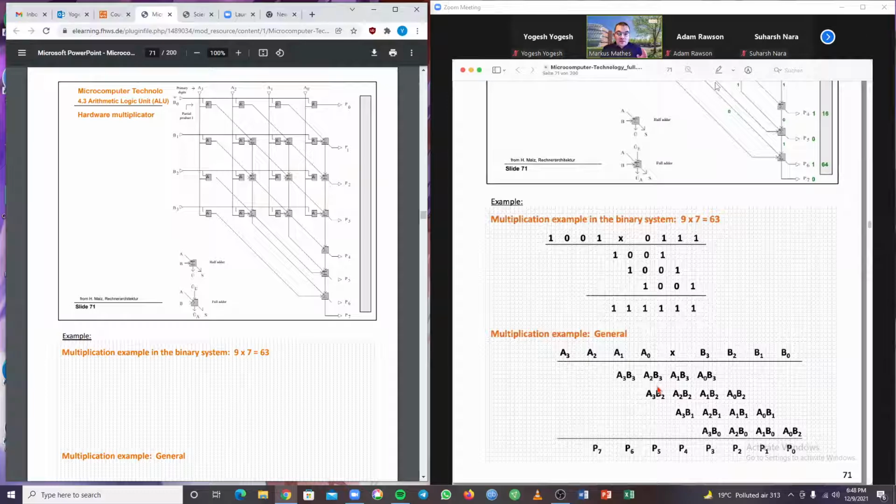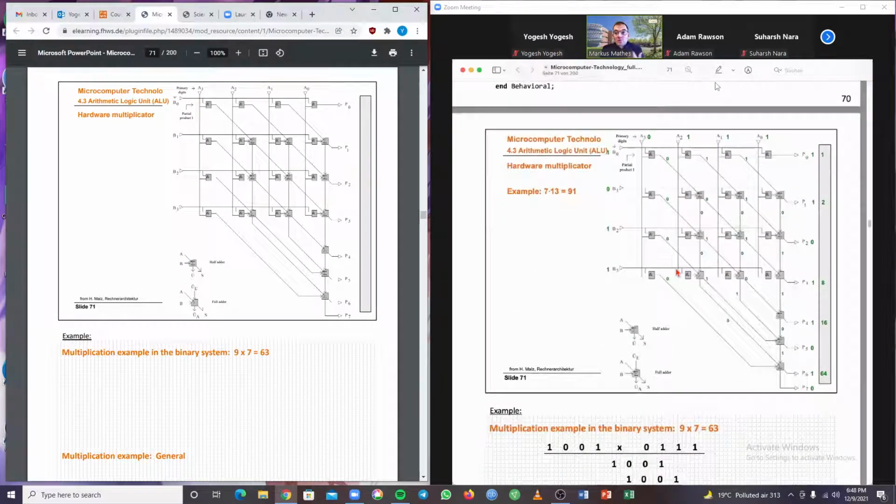in the second factor. We did this example together, and we saw that in hardware, or in the binary system, a multiplication boils down to copying the first factor several times, making left shifts depending on the position, and then making an addition. This leads to one possible implementation in hardware using half adders and full adders. Then we discussed this matrix structure that does exactly this.